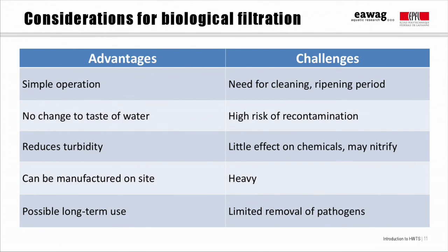Well, let's consider then some of the advantages and challenges of biosand filtration. First, operation is quite simple. You pour water in and you get filtered water out. But it does need regular cleaning, this swirl and dump method, and the filter should be left to ripen after cleaning, so that can be a challenge.